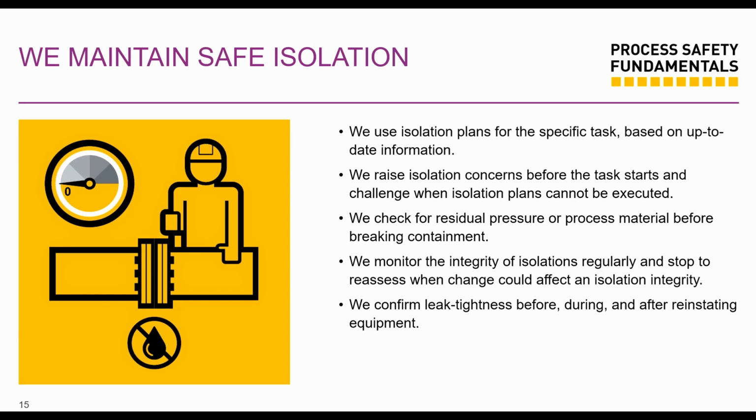The next is we maintain safe isolation. That's the fifth. I think everyone needs to understand how important and critical safe isolation is. This is so key. And you want to have your positive isolation. You want to make sure that stuff is staying inside the pipes. We use isolation plans for the specific tasks. So based on up-to-date information, we want to make sure that we have all our isolation plans in place.